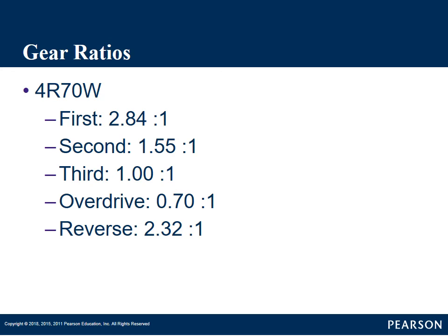Not only are the vehicles heavy, the stuff they're going to pull is going to be heavy. So we want to adjust our gear ratios. They're going to be a lower gear. In other words, the numbers are going to be higher to give us more torque multiplication.